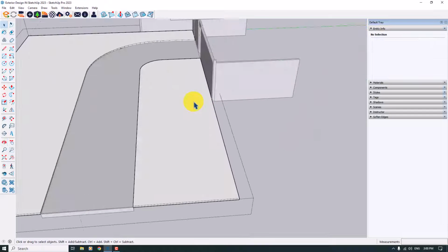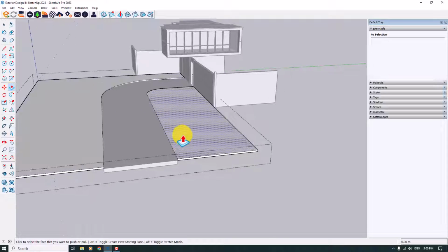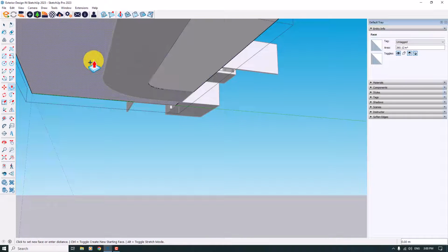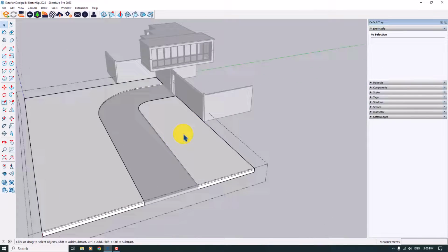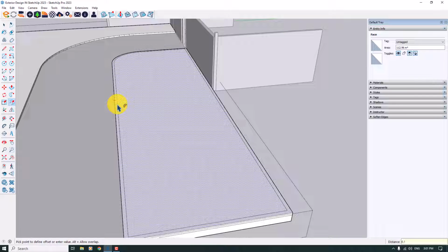It's really wonderful detail when you use Lumion or Enscape for rendering these type of jobs, because your area is completely detailed and it works in different type of render engines very wonderful. So I will click on the offset option, use the offset, and create some offset for my edges in the street, about 13 centimeter.